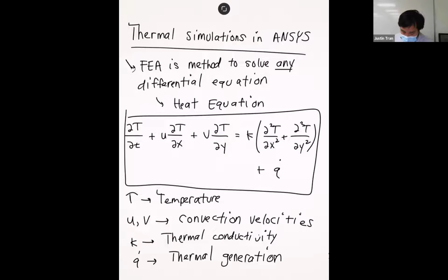The equation is different than structures, and of course all of the material properties, solution variables, and boundary conditions are going to take different forms because we're solving something with completely different physics. But just because it's a whole other equation doesn't mean that we can't solve this with finite elements. What I hope to prove to you today is that we can take all of the knowledge we've gained in this class on structural finite elements and apply it in a different way to thermal. The idea is to take a thermal concept and map it onto a structural concept.